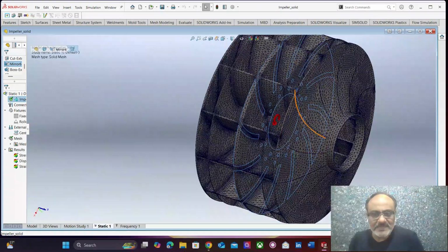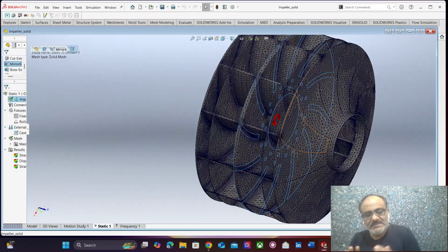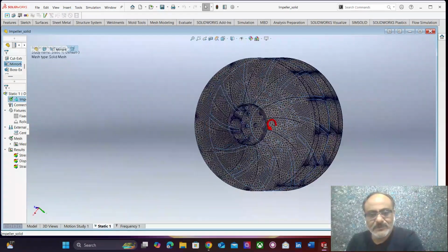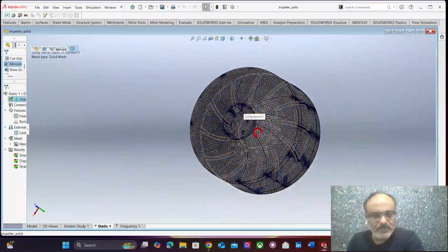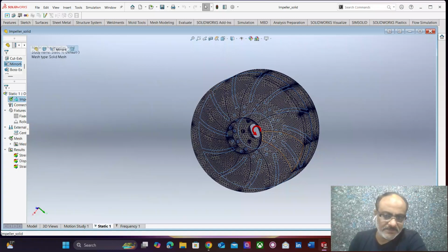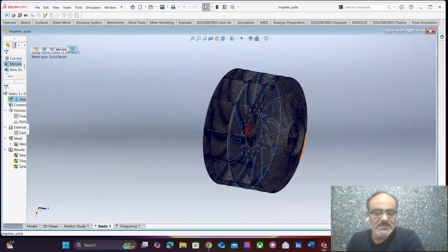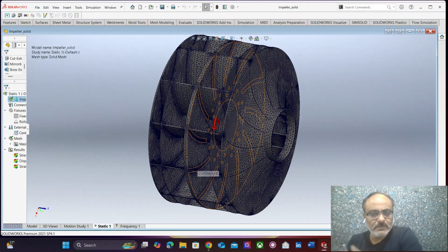So in that central region, we had increased the thickness by adding 2.5 mm thick plates, and we have bolted it using 22 mm dia bolts. So the internal bolt holes are all bolted using 22 mm dia bolts. So now this particular system is subjected to simulation.